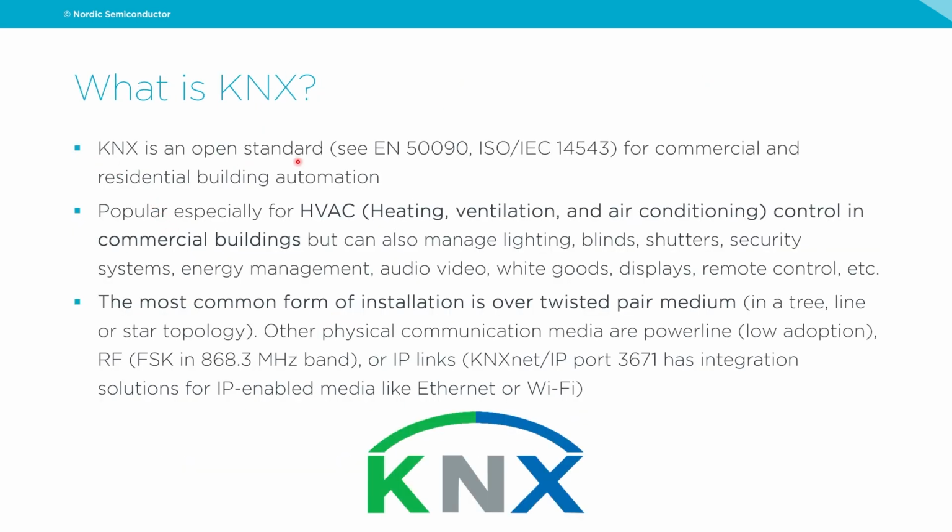KNX is an open standard, and it's mainly deployed in commercial and residential building automation. Commercial buildings would be things like office buildings, airports, shopping centers, these types of buildings. And it's popular especially with HVAC control. HVAC stands for heating, ventilation, and air conditioning. So in these commercial buildings, but it can also manage other types of devices like lighting applications, blinds, shutters, security systems, and many others. KNX is most commonly deployed and installed as a wired infrastructure using a twisted pair medium that can be in a tree, a line, or star topology.